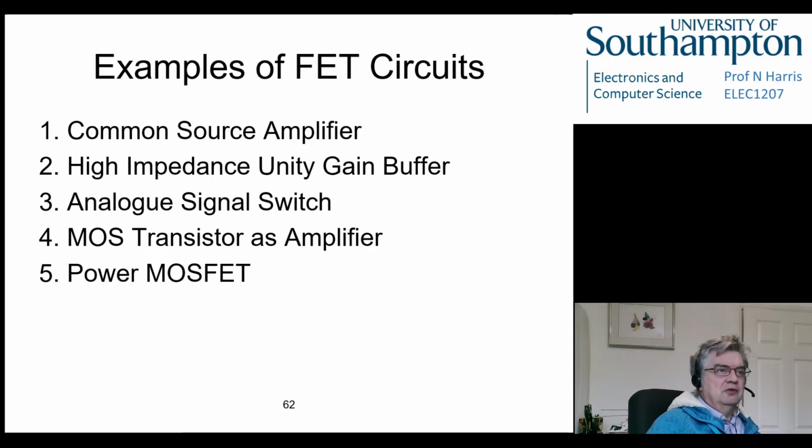showed a little bit about the sort of equations that might apply, and there was a couple of key equations because there's two main operating regions of a FET, a flat area and a more, well, linear area, a rising area should we say, and the FET allows us to use either or both of those areas in useful circuitry. So we're going to look at a few circuits now and get an understanding of how we can use these FETs in proper devices. So we're going to look at something called a common source amplifier,